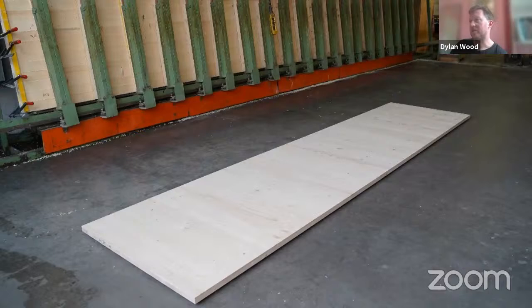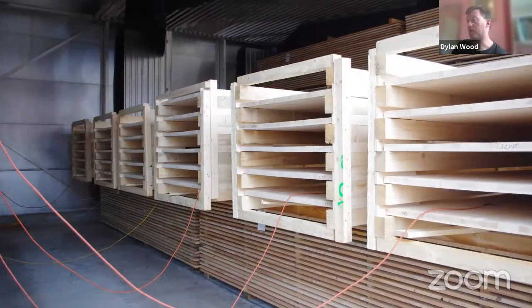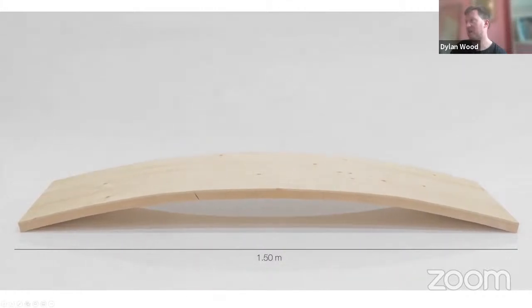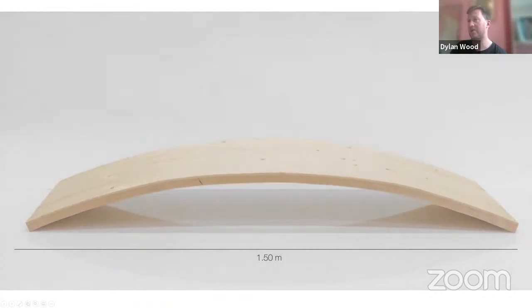So after the boards are selected, they're manufactured into these 2-layer plates using a standard press. And then they're put into these racks, like what you see here, and then into the kiln where they will be dried alongside all of the other boards that are used for other applications in timber construction. And inside the kiln, this is where the sort of magic really happens, because over a couple of days during that drying, each plate shapes into this curved geometry with a 2.4 meter radius.